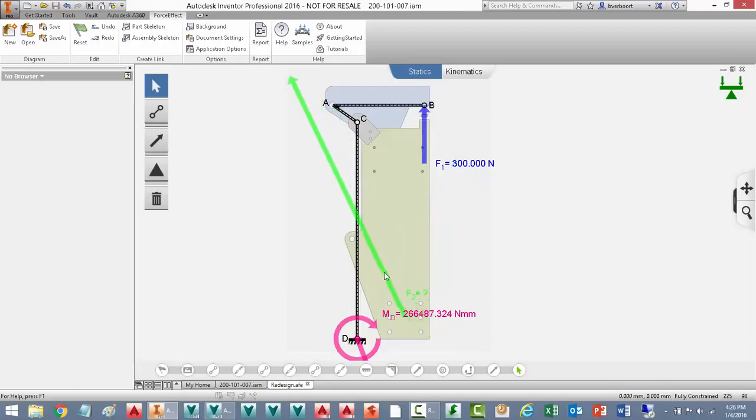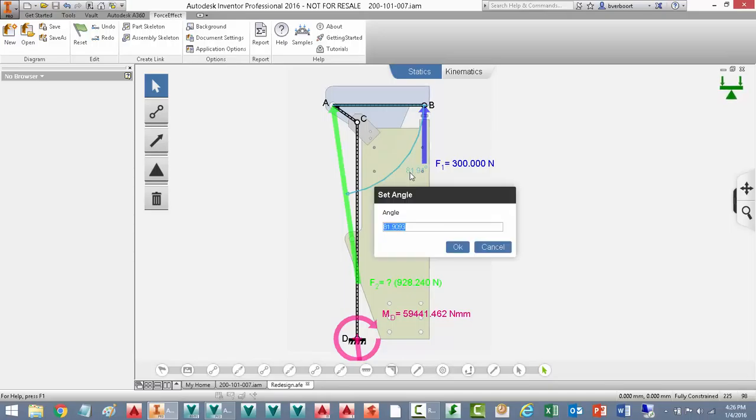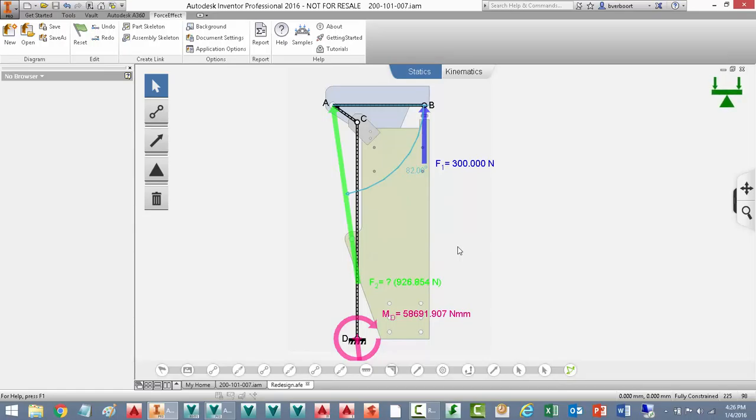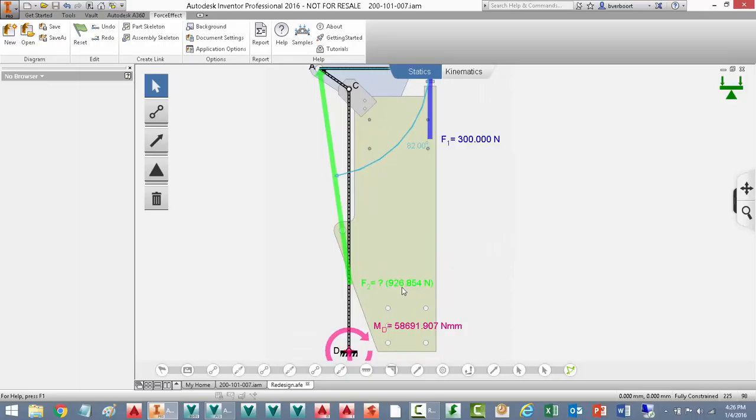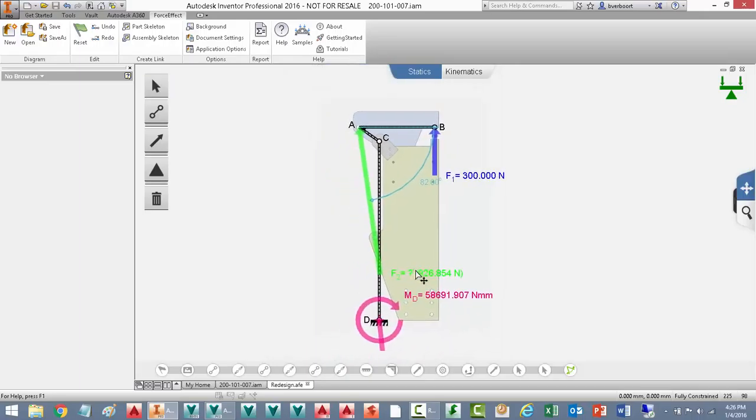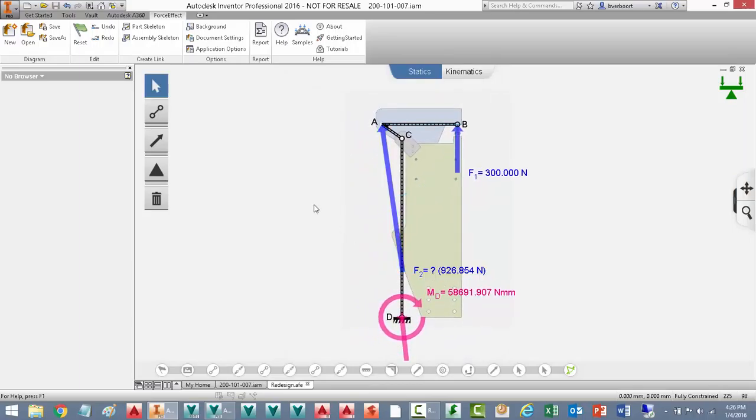If we move this further, a little further, pivoting it to the connection point, which is roughly 81 degrees, or I happen to know it's 82 degrees, then we'll discover that we're getting roughly 1,000 newtons required. So I'm going to zoom back out just a little bit here to incorporate the entire design. Then I can make a report of the statistics that are here.